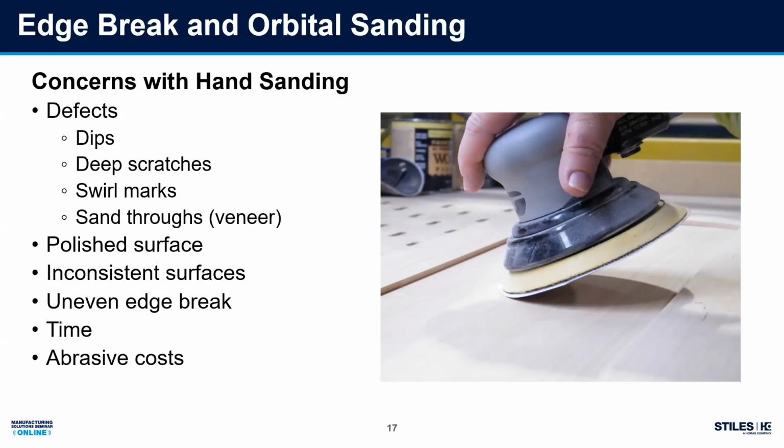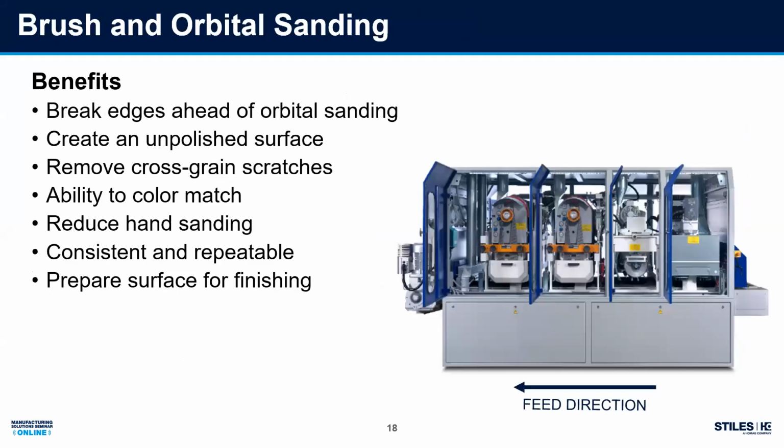Another challenge here is if you've got 4 people breaking the edges of these cabinet doors in your manufacturing process, and one person is too aggressive on those corners, maybe you don't really notice because you're talking about 10 or 15 thousandths difference of more round over. Then it goes to finishing, then it goes to the homeowner, and they want to know why 1 out of 4 or 5 doors has an inconsistent surface finish versus the rest. So we can talk about how to eliminate that.